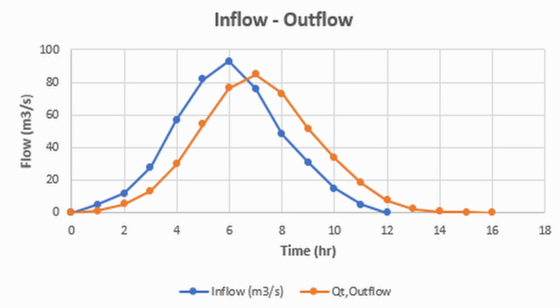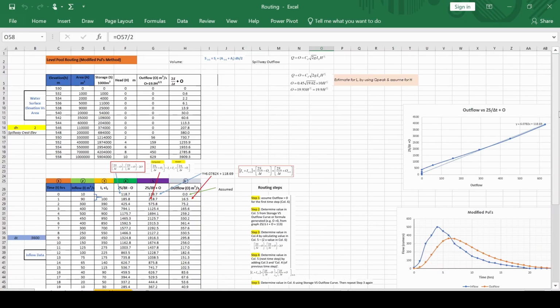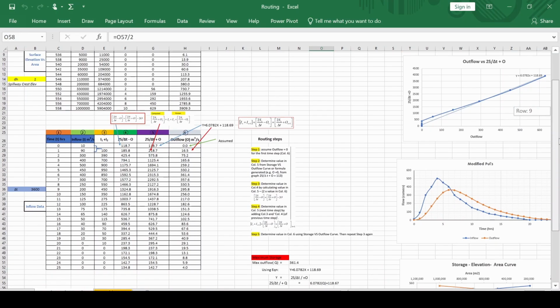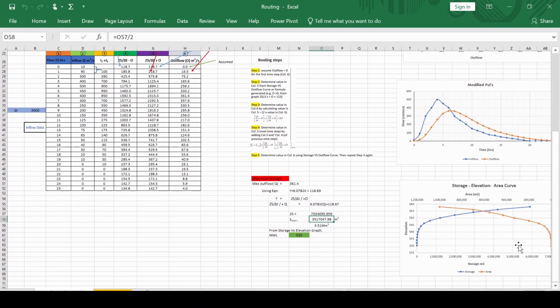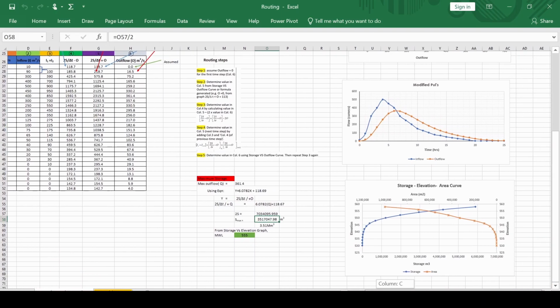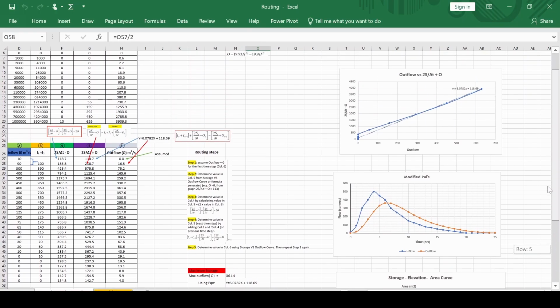Now, this hydrograph finally helps us come up with a peak discharge of the inflow. So once we have the PMF hydrograph plotted, we now make sure that we do reservoir routing. Once the flood hydrograph is known, engineers perform reservoir routing, and reservoir routing normally calculates how the flood behaves inside the reservoir.